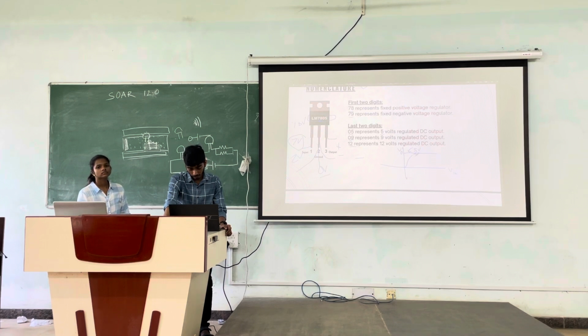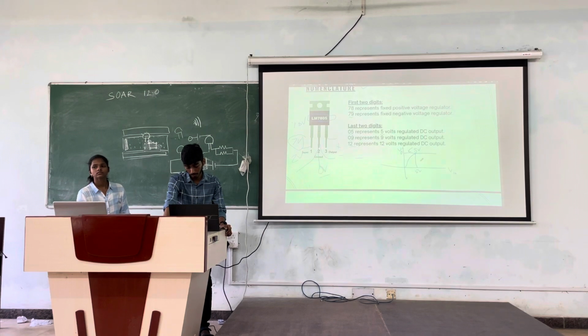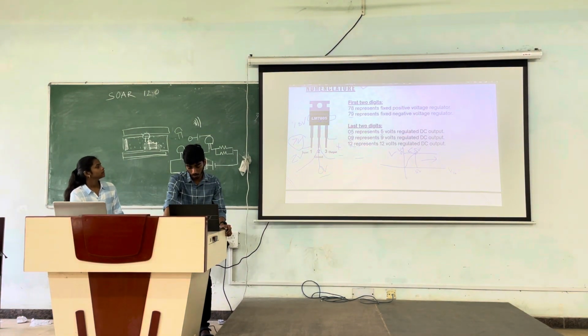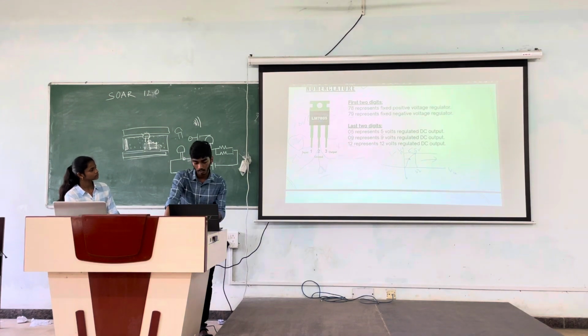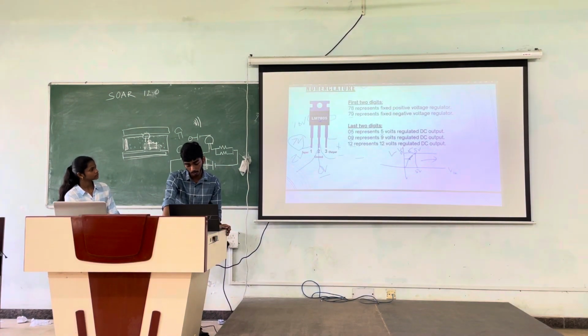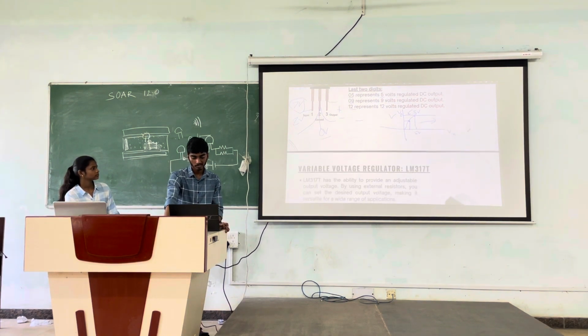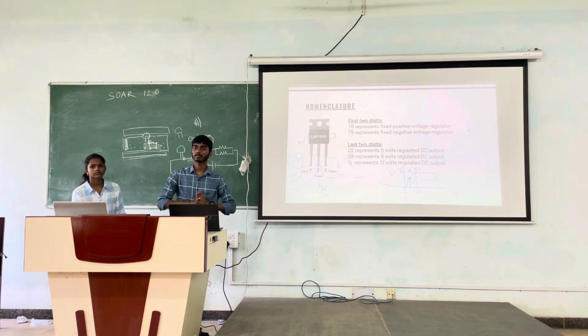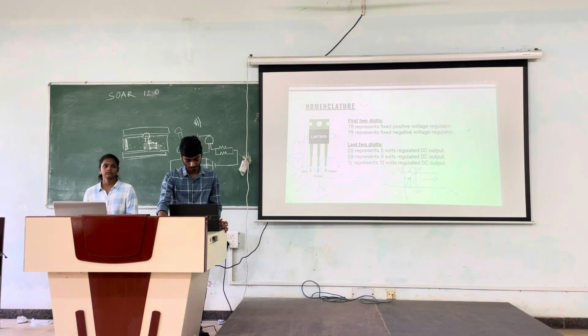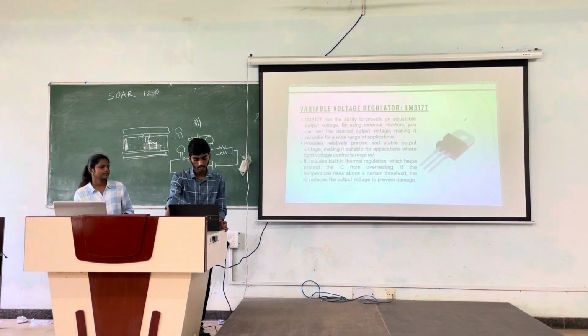Above 5 volts, it will maintain this constant voltage of 5 volts here. But if we drop the input voltage below this, we will not get 5 volts here. We'll get something else. If we apply a lower voltage, we'll not get 5 volts. So these are some basic things. Are you getting these things? Okay, let's proceed further.